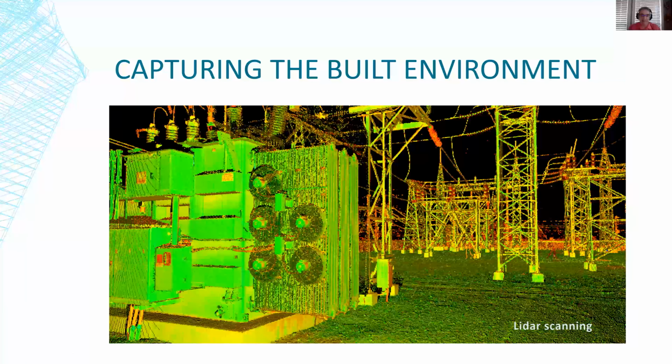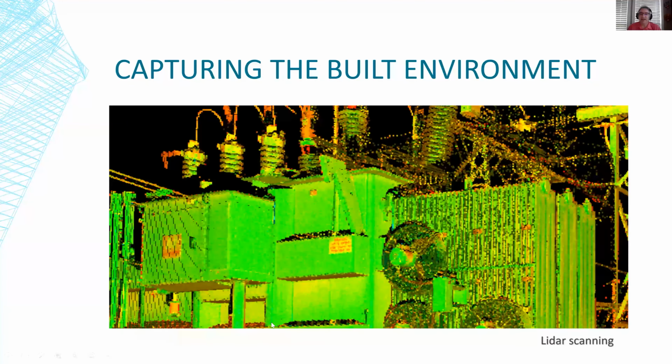LiDAR scanning is millimeter accurate. However, you have to have lots of different scanning stations. I'll get to that in a minute, but first, what LiDAR scans produce is a point cloud. What might appear solid right here is nothing but a massive amount of points, and you can see it here in the top.